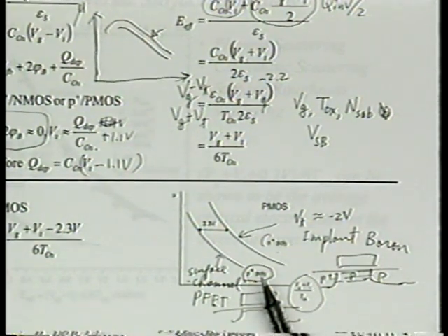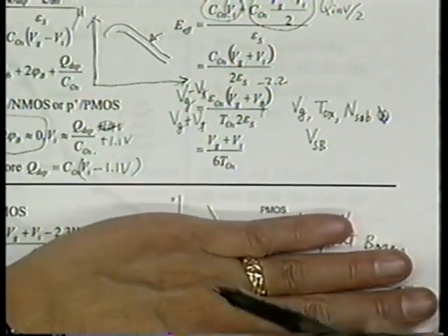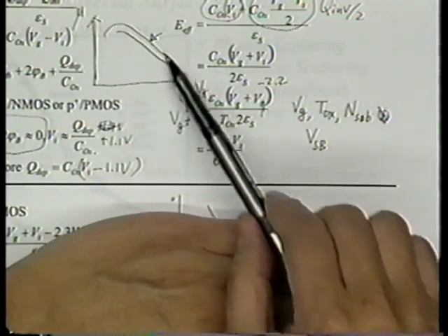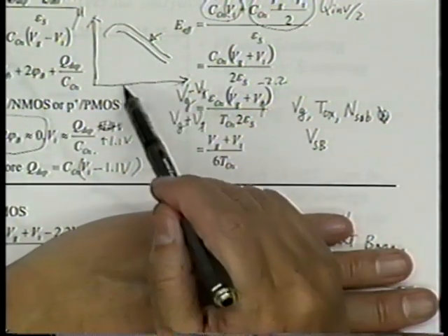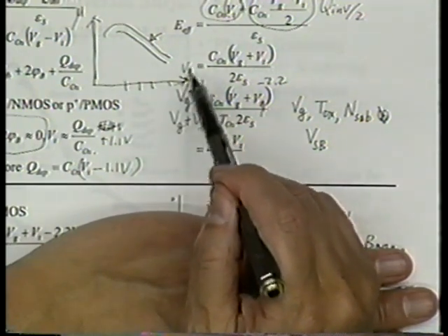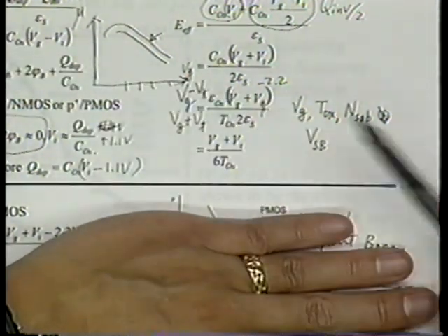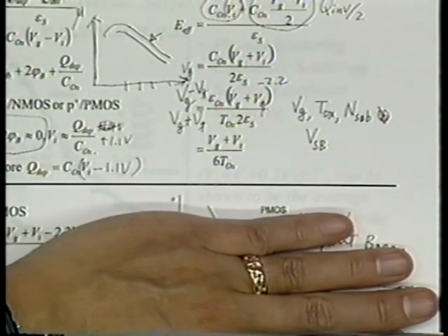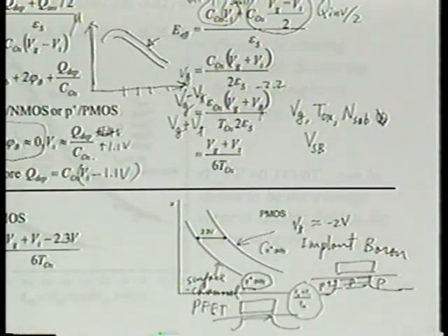So let's go back to the N-channel transistor. Before I started this topic, you had no problem understanding the curve should look like that. Is that right? Certainly at every one of these points of different VG, we're talking about surface channel, right? Is there any question we're talking about surface channels throughout? Yet, just because the vertical field is higher, mobility can be different. So why can these two transistors not have two different mobilities even though both are surface?